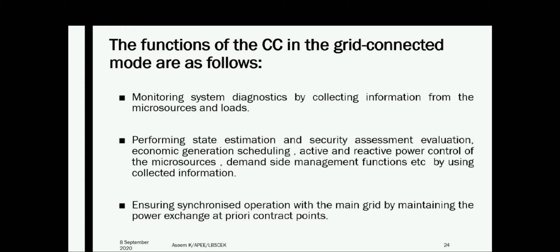Then there are some typical functions for central controllers in the grid connected mode, listed here. It works as a monitoring system for diagnostics by collecting information from the micro sources and load, and performing state estimation, security assessment evaluation, economic generation scheduling, active and reactive power control of micro sources, demand side management, etc., using the collected information.